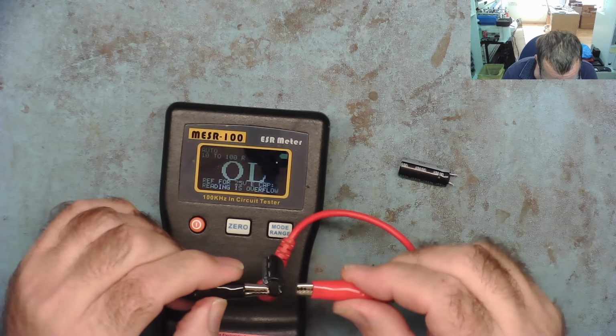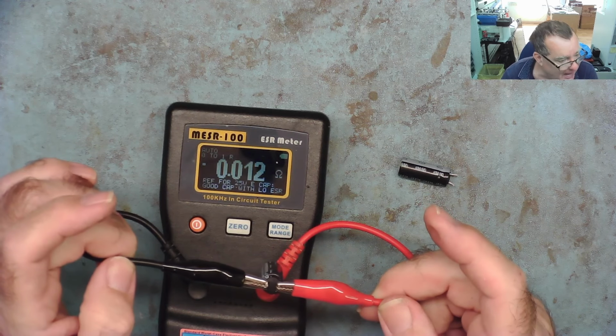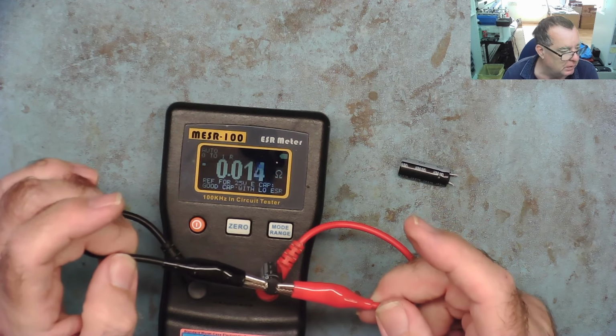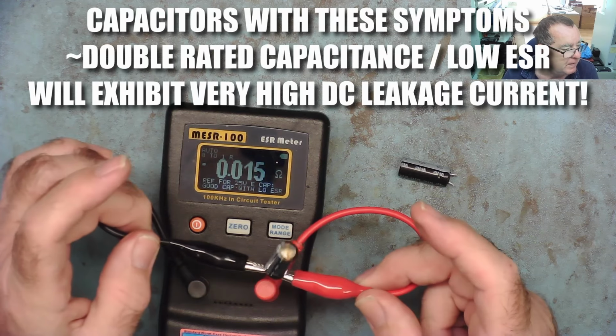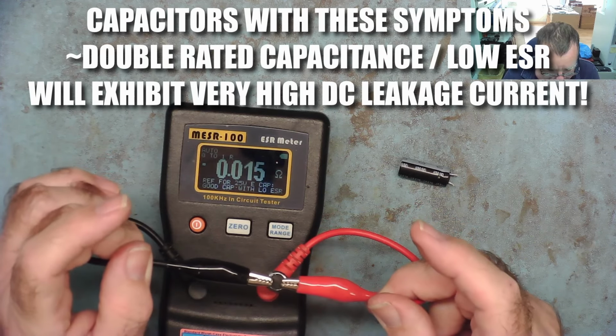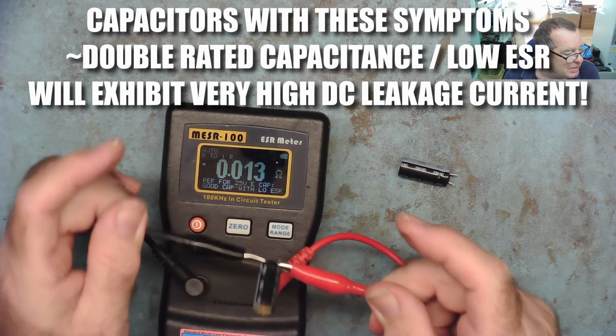But we can have a look at the capacitor. See, now that reads good ESR, but the capacitance is about double what it should be, and it's visibly a bad capacitor. That's something to look out for. Some capacitors, certain brands or types, will fail in this way.